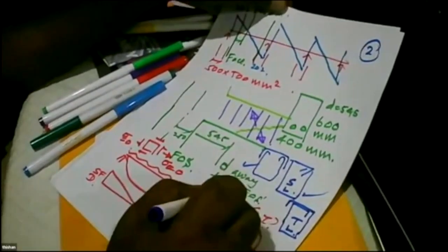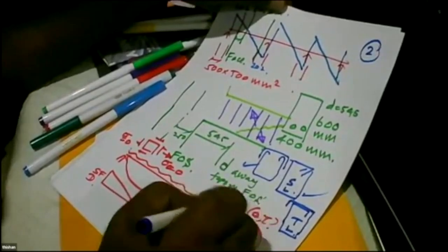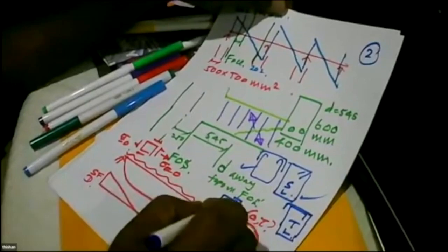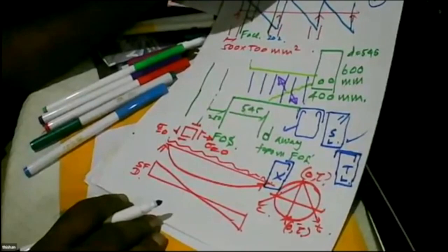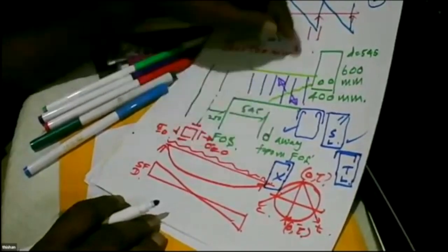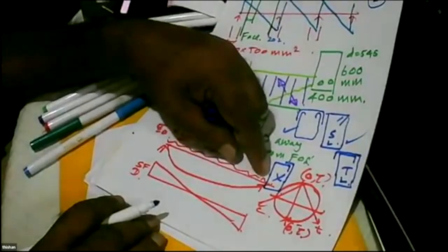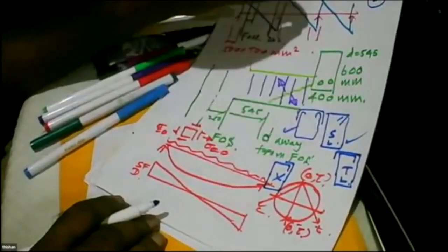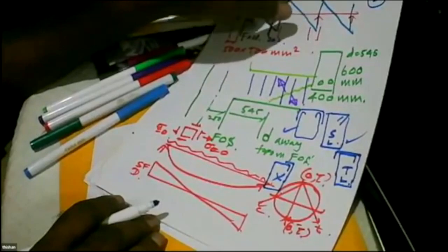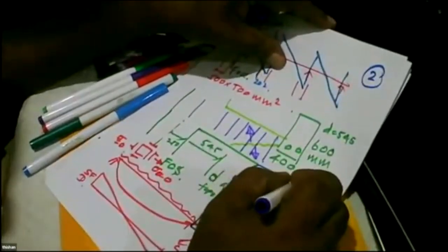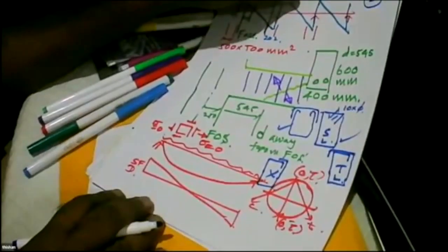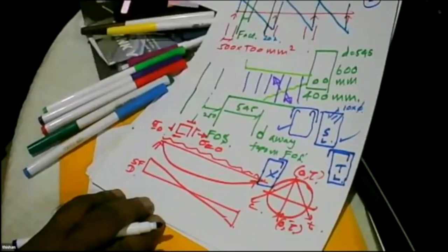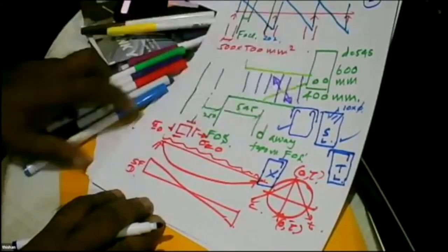What is not possible? This is not wrong. But the new link bending machines, they give you this. So you can buy this, but ask a man to bend like this and make it like that. And I generally keep this length as 10 times the diameter of the link, because I would like to lock it. Generally what you need is 6 times diameter. Generally I keep about 10 times diameter and bend.